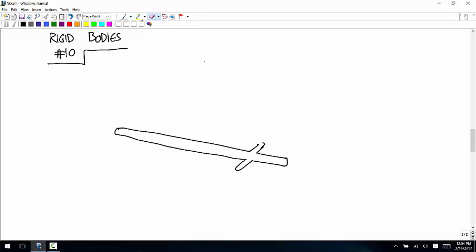And this cross piece has a pulley. And then there's a pulley on the body over here. Okay. And we're neglecting the weight of the body, so there's nothing at the center there. There's 140 pounds acting down here. There's a cable tension, T1, acting there. There's a different cable applying a cable tension T2 in that direction.